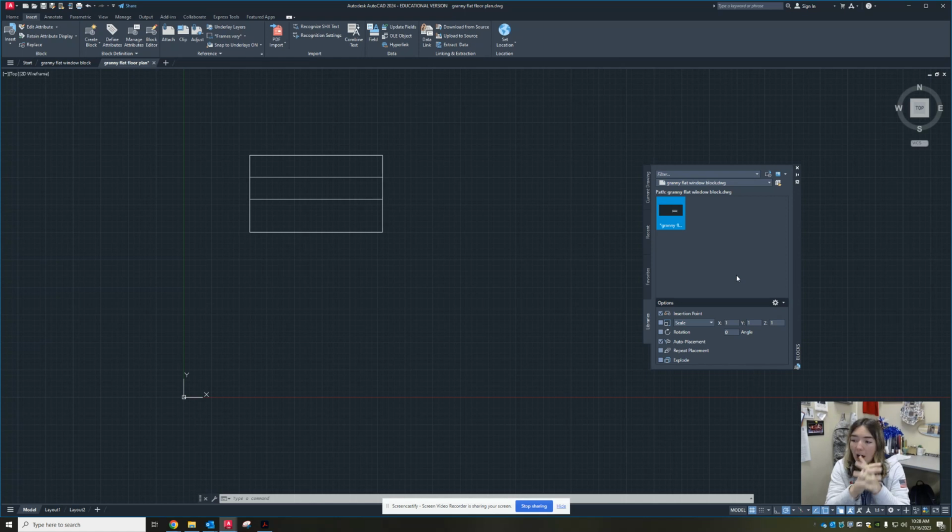The next one is Y. Y is referring to your height in your drawing, right? And our windows, because it's 2D and we cannot see the height because we are looking at our drawing from above, we can't tell how high up the window goes. That is also irrelevant and can stay 1. The final part that cannot stay 1, that will be changed to help us change our window widths, is X. X currently is at 1.